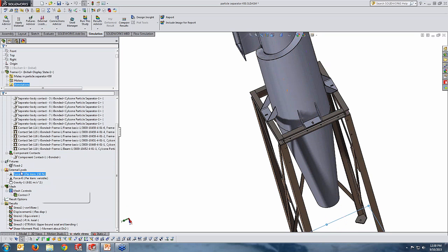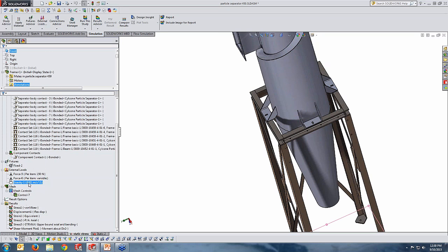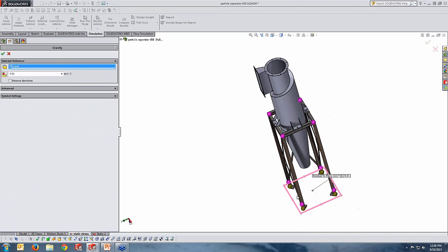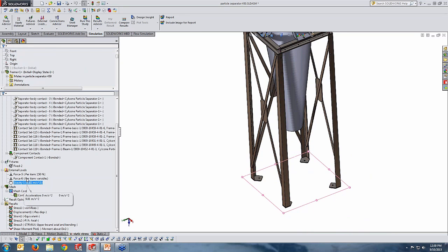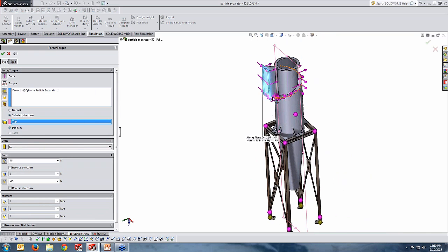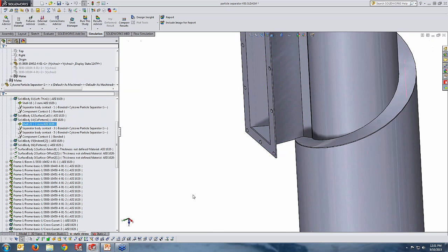I have activated the gravity like here and made it 9.81 meters per second squared, let's say normal to the front plane. And my next force, which is getting applied on the shell intake using the face, 2 component 45 minus 75 according to the top plane. Okay.